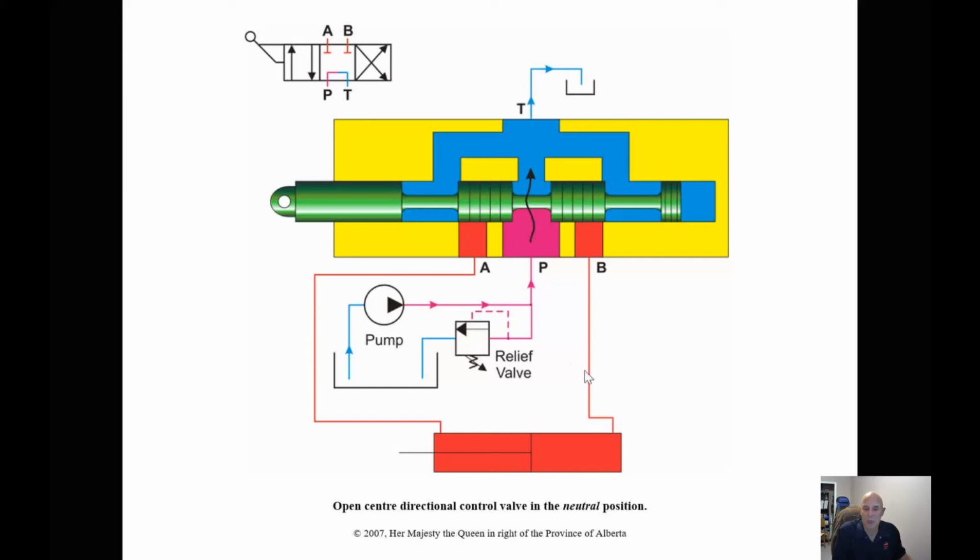We talked about open center and closed center systems. Again, in an open center system, the pump displaces the fluid. The fluid is always returning to the tank until we start to block off the flow of fluid, which then creates pressure in the system. If we take a look at the schematic, we know that an open center system has a line that goes all the way through, so we know the fluid is flowing all the time.